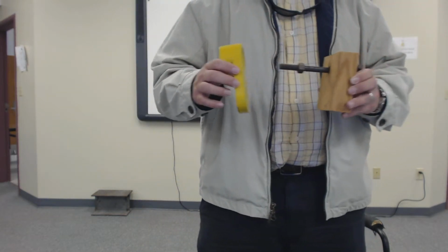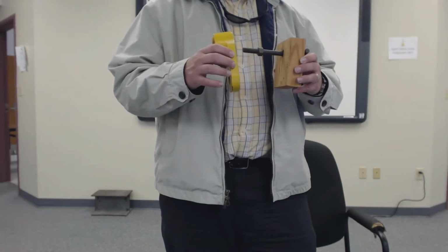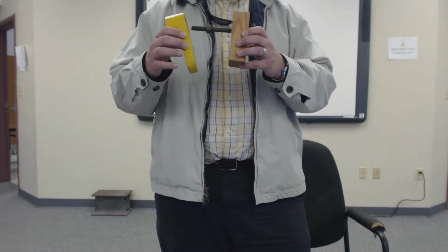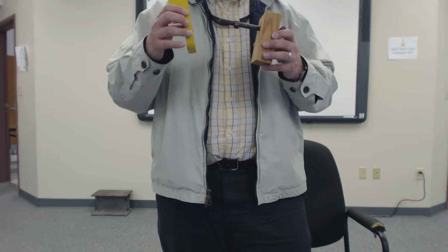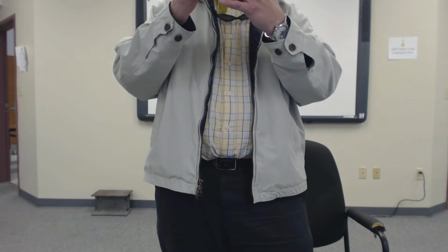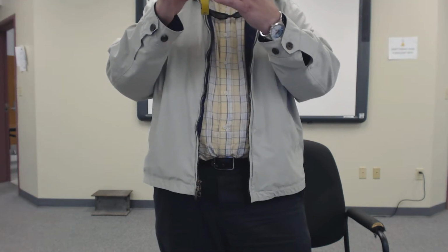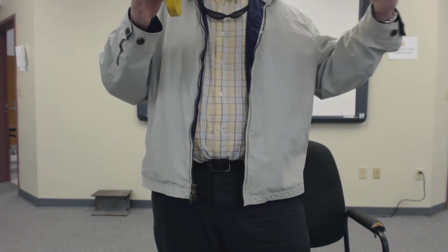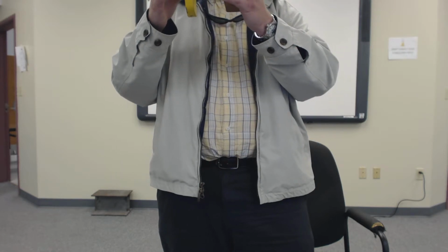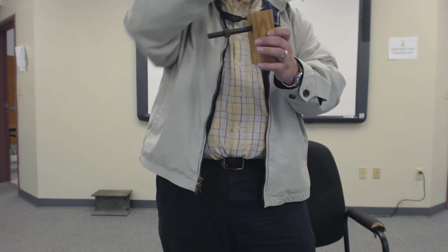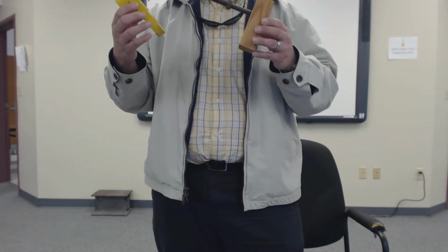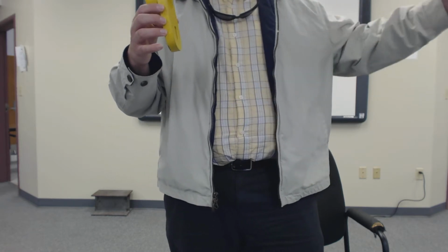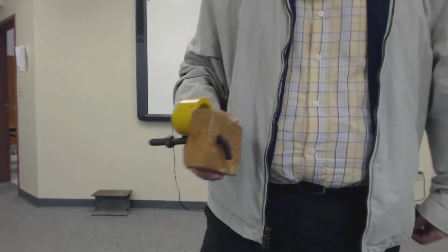In the middle of the wall, it sets 16 inches on center. That's fine. But think about putting a piece of plywood up on the edge. Do you put it at the center of the stud on the edge or not? The very first one, no, the plywood has to go all the way out to the edge. So you just lost 3/4. So you basically have to move your whole system 3/4 this way so that now your plywood fits all the way down. Does that make sense? So you're moving your first stud over 3/4, and then it falls out. Then you do 16 inches on center from there on out.